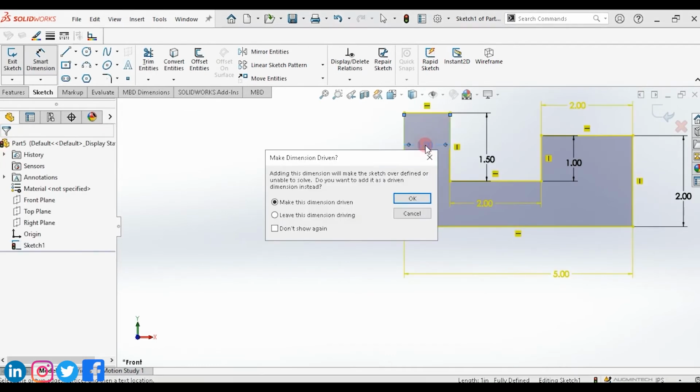I want to set it 1 inch, but a warning or error comes. What is this error? It is saying Make Dimension Driven. It means adding the dimension will make the sketch overdefined or unable to solve. Do you want to add it as a driven dimension instead? The meaning of this is that I have set the dimension of this line 2 inches and the dimension of this line 2 inches. This is a total of 4 inches and 1 inch is left.